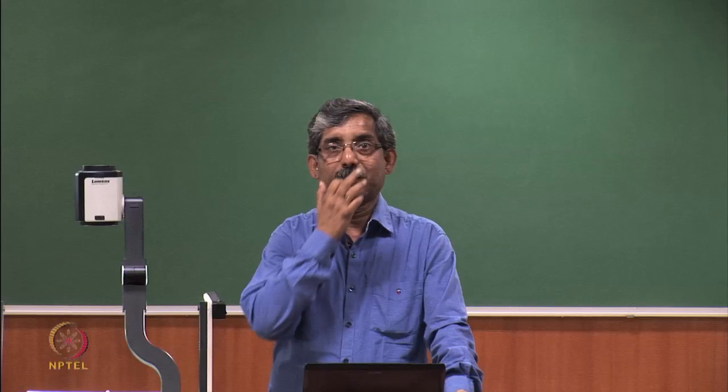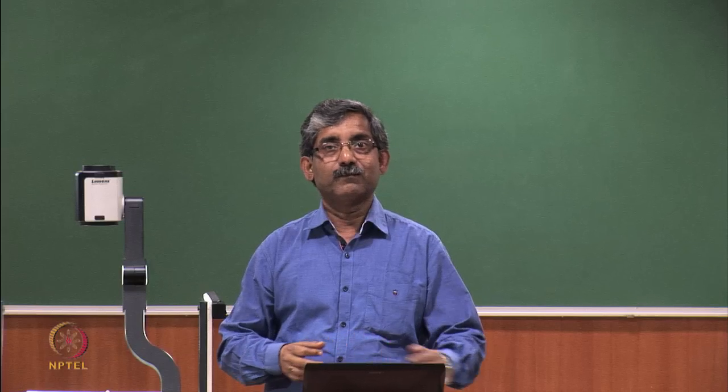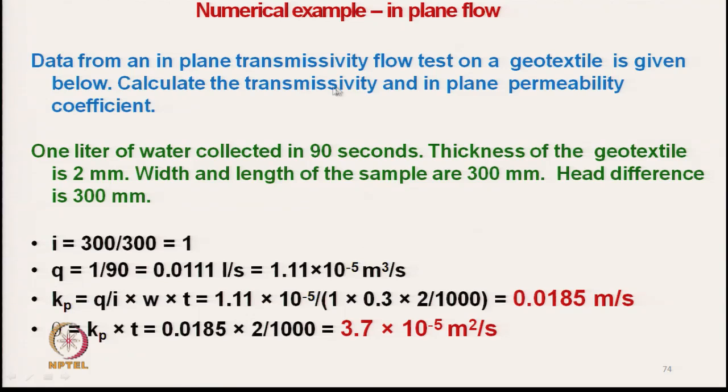Now, let us see one practical example. Data from an in plane permeability flow test on a geotextile is given below. Calculate the transmissivity and in plane permeability coefficient. 1 liter of water collected in 90 seconds.